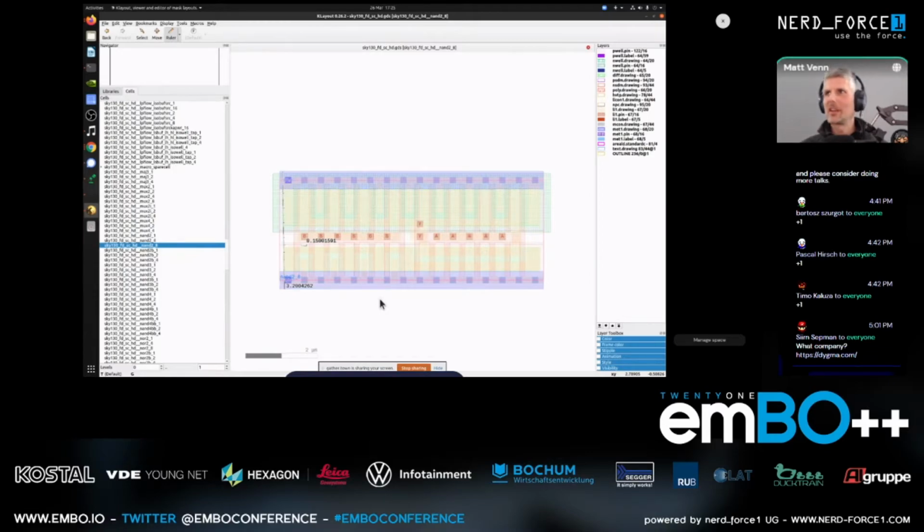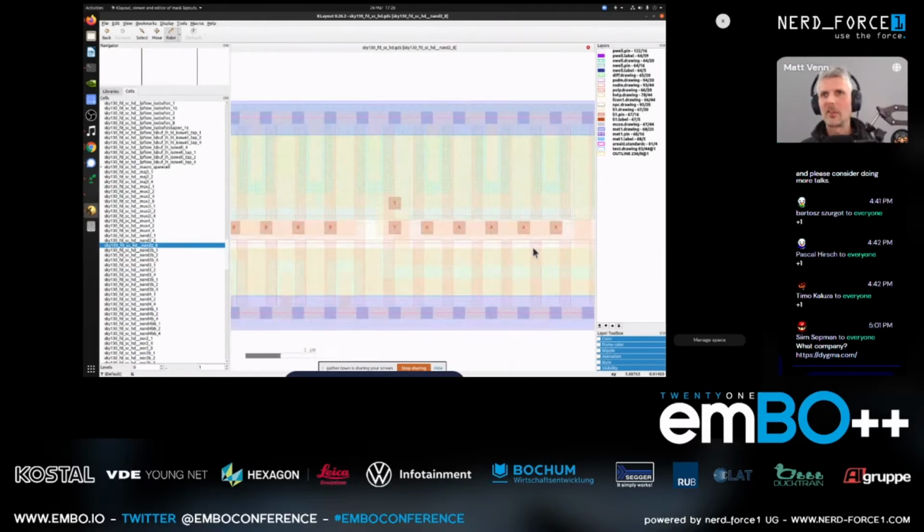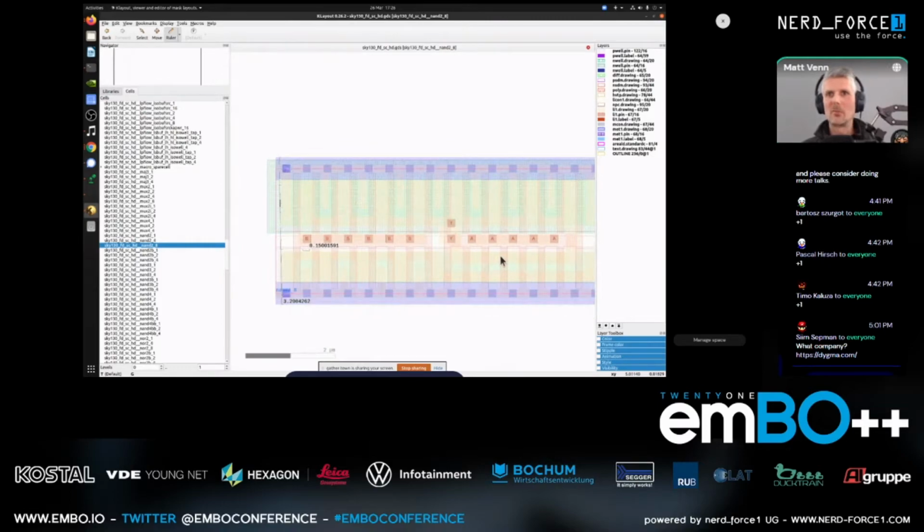So the reason we want something like this is because it depends on how many other things we're driving. So if you think of like the clock in a microcontroller, it's got to drive thousands or tens of thousands of logic blocks, whereas like one signal that drives whether a GPIO should be an input or an output probably only needs to drive one gate. So if we've got a clock and we want to drive it hard, then we use something with big ganged outputs. So all these MOSFETs, they're all connected together. 1, 2, 3, 4, 5, 6, 7, 8. And that makes an 8 times drive strength NAND gate. So we can use that to drive much bigger trees of logic.